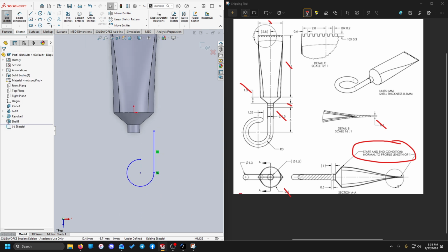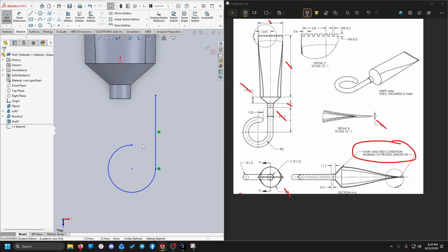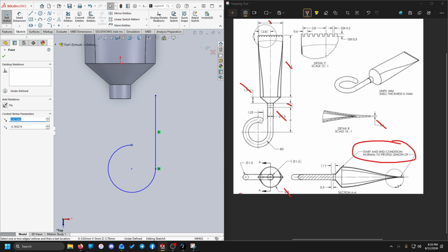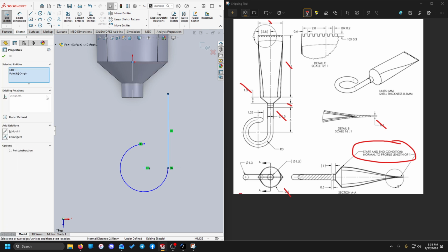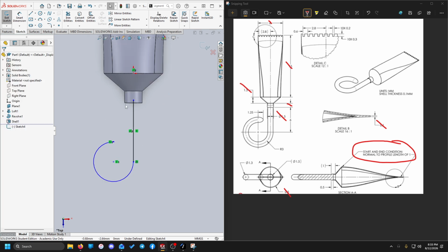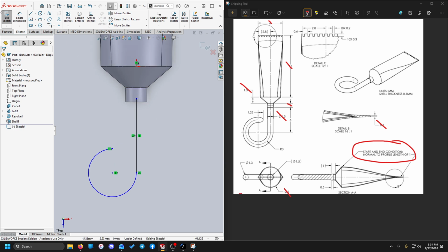Looks like it goes straight down, then we've got a 3/4 arc here. So in order to get that dimensioned or defined properly, we can end up taking the end point of the arc, and that looks vertically aligned with the center mark of it. So those 2 points, vertical. Nice. Then we can start positioning it, so the central axis remains consistent as we continue along. So we can just grab our edge, grab our center mark, or origin, sorry, and make them concentric together.